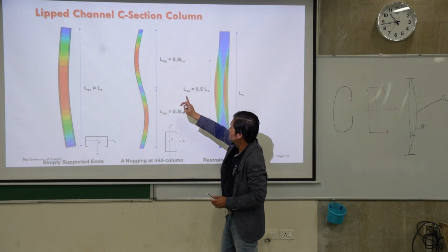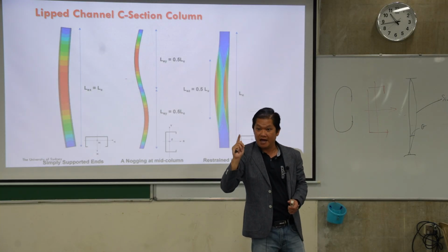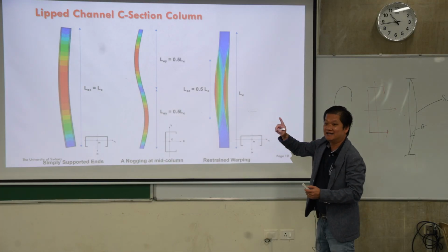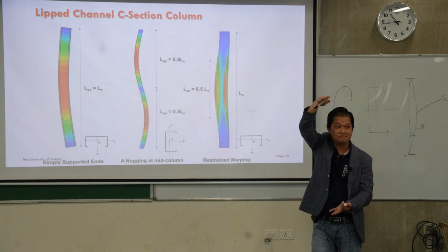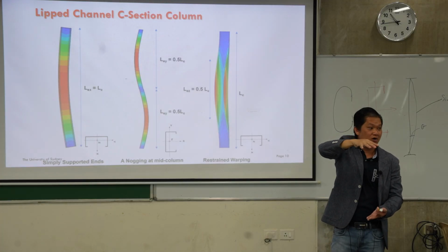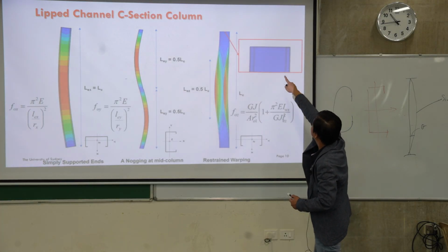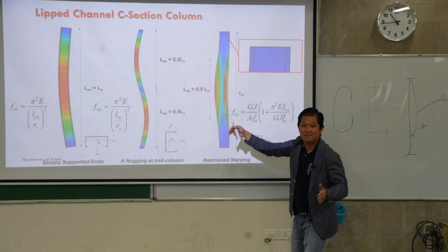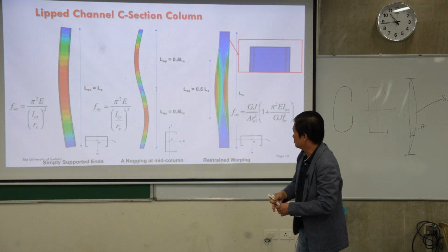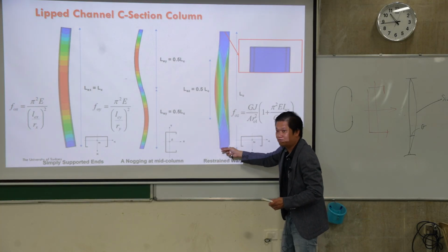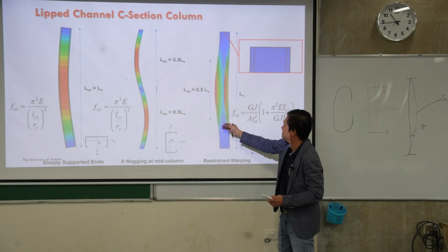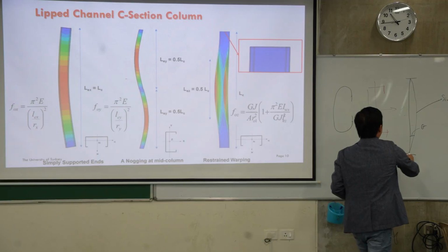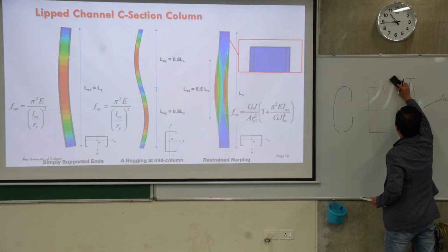That's why in the equation you put 0.5 L, not L. Importantly, when we welded the top chord to the bottom chord, I don't have the warping displacement in here. It is exactly like you fix something. So right at the end, because you fix that one, it takes a little bit of time before it starts to twist, and then twists in here. So our twisting displacement now is like this one.